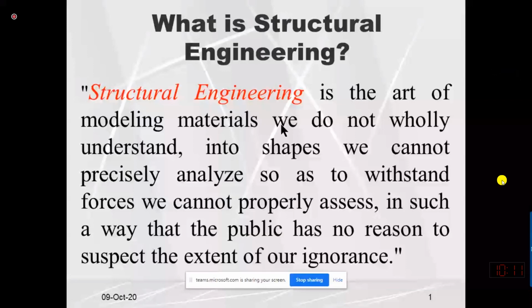These are also not 100% accurate formulas, because we derived them by assuming certain assumptions. What assumptions? That the material is perfectly elastic and the cross section remains plane. But actually the material does not behave like that. It means that, again, in order to compute those stresses, we have considered a lot of assumptions. But those assumptions are realistic, close to reality and based upon engineering principles.